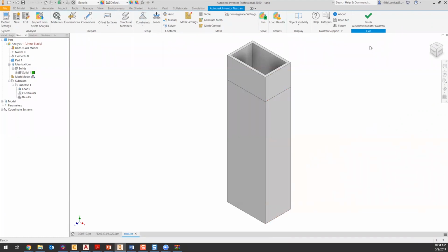Now, previously, you could still do this. Some of you, if you've attended the Nastran In-CAD trainings, may be familiar with a water tank example where you have a varying pressure with height. That's okay to do. There's nothing wrong with doing it that way, but it's a much more manual process, and it's a lot easier to go wrong that way. Now you have a specific load type just for a hydrostatic load. And so I'll set this problem up with a very simple method.